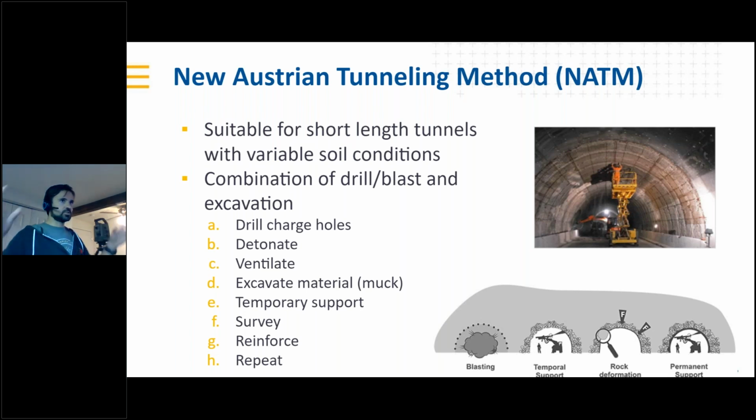So this could be the arch, the ribbing along the side, usually surveying for the next section, so understanding the geology as well as how much material has been removed, and then reinforcing, usually by shotcrete, rock anchors, and a variety of other things. And then this is repeated every so many meters, depending on the geology and the surface. So it could be every meter that we have to do this process, maybe every 5 meters. So it's a very iterative process.